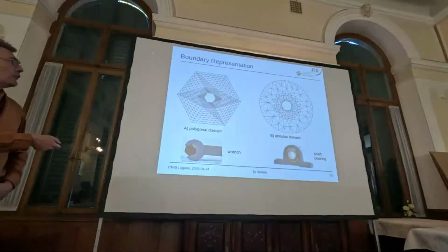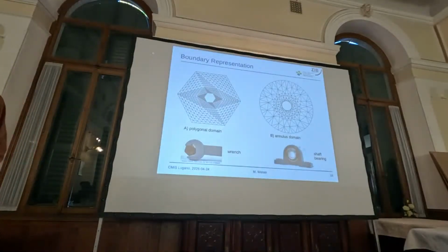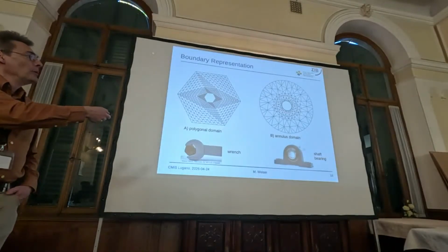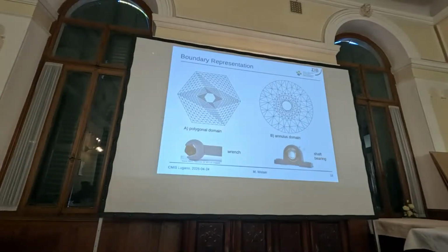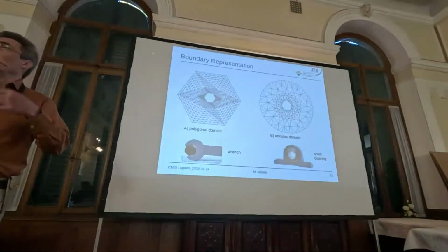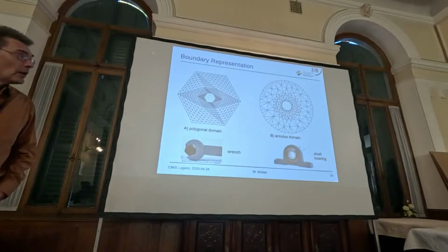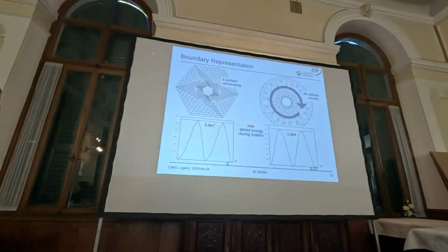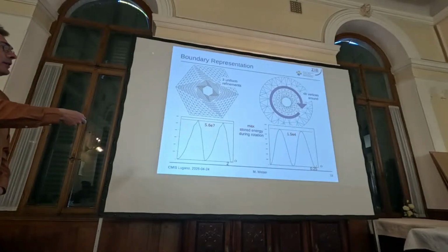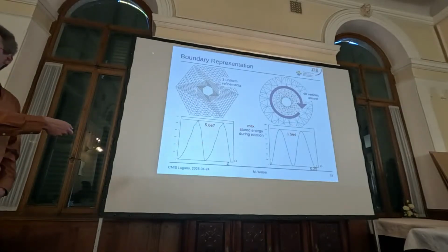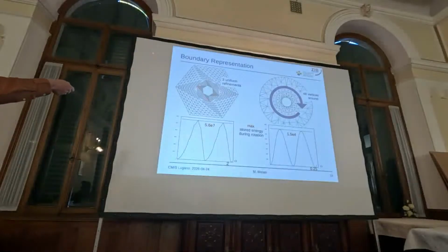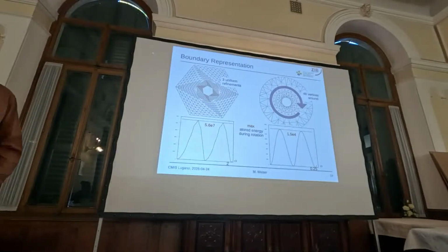This could be a kind of wrench where this is actually the geometry, just with a coarse grid, or it could be a very coarse discretization of something like a shaft bearing, where we expect we can rotate the inner annulus without any contact force whatsoever. So let's compute both and rotate this. We see here the stored energy over the rotation angle. And of course, when we are in that configuration here, we have quite some deformation and some energy.